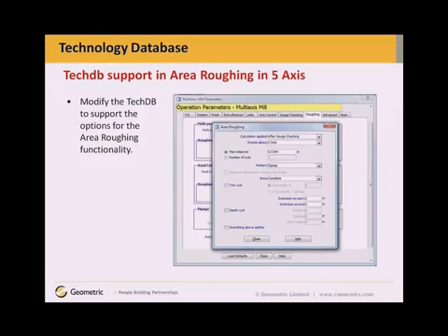In CAMWorks 2010, we have added these parameters to the technology database. This now allows you to save the default settings in the technology database. Settings such as rotation about z-axis, step over, and other parameters.